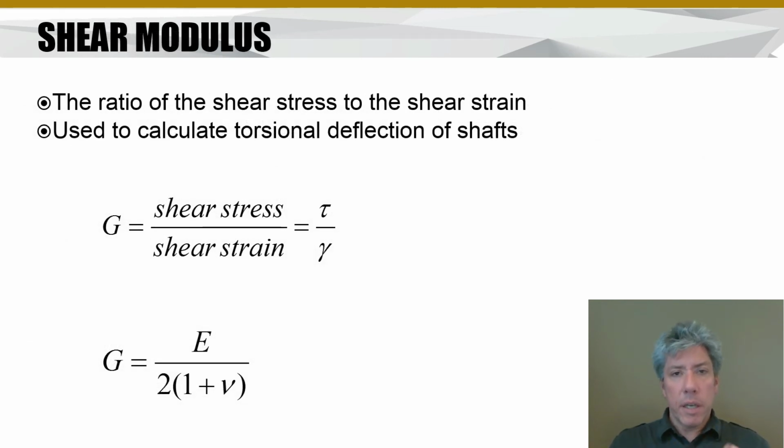Now, similarly, when we're talking about shear stress, remember we were rotating the element, so we had shear strain. There's also a relationship between the shearing stress and the shear strain that results from the shear stress. Just like we took sigma over epsilon, now we're going to take tau, the shear stress, over gamma, the shear strain. That ratio has a name, and it's called the shear modulus. We give it the symbol G, like we give Young's modulus the symbol E, capital E and capital G.